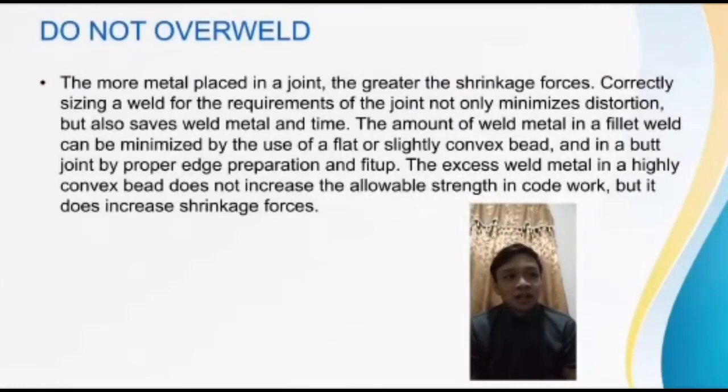And lastly, do not overweld. The more metal placed in a joint, the greater the shrinkage forces. Correctly sizing a weld for requirements of the joint not only minimizes distortion, but also saves weld metal and time.